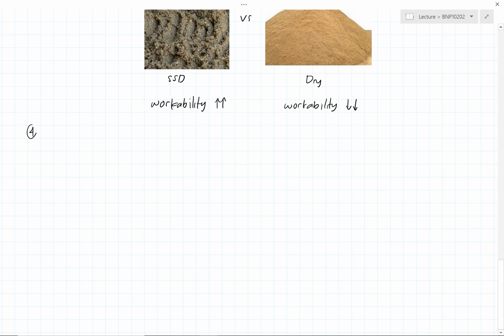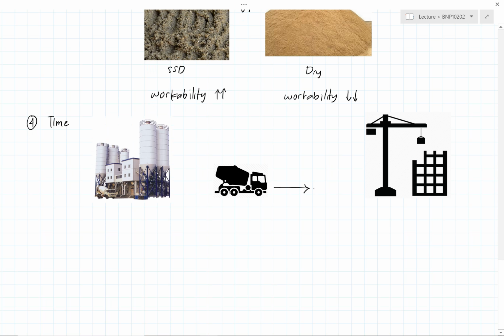The next factor is time. Time plays a crucial role here because the hydration of cement takes time. Eventually, your concrete will harden later on. But how fast or how long the hydration takes place, that is the question. Sometimes you need extra time to deliver your concrete. I use this example a lot.